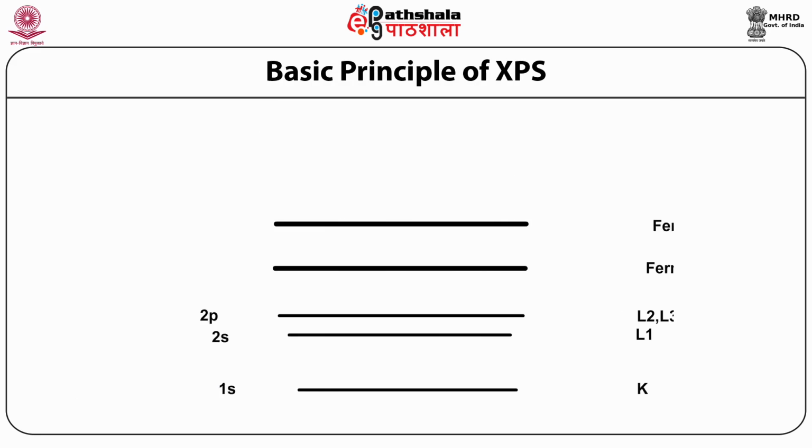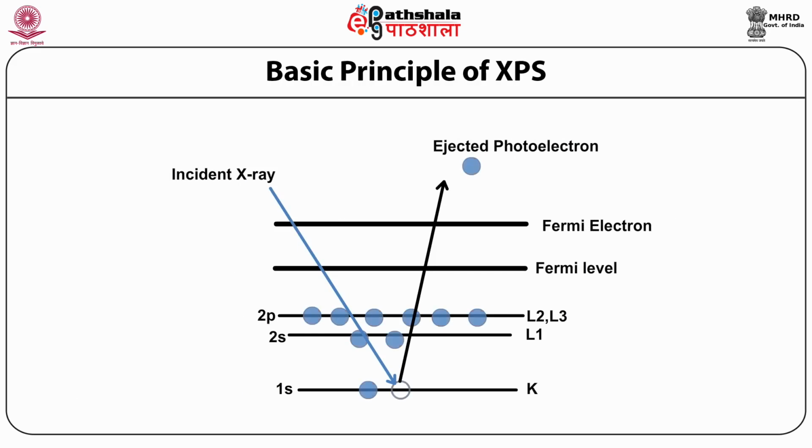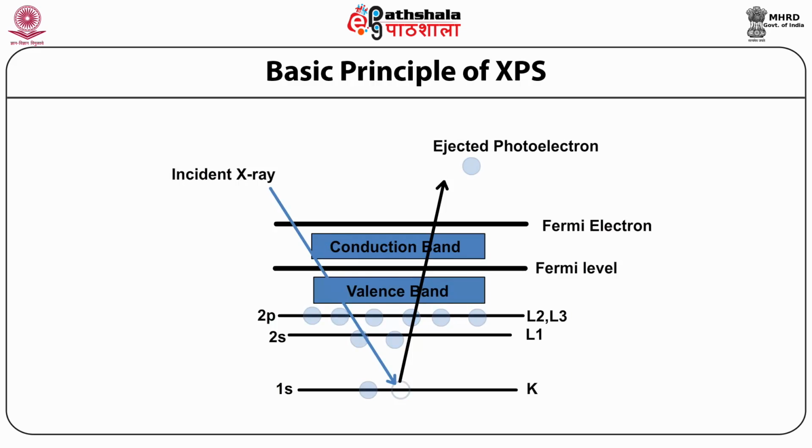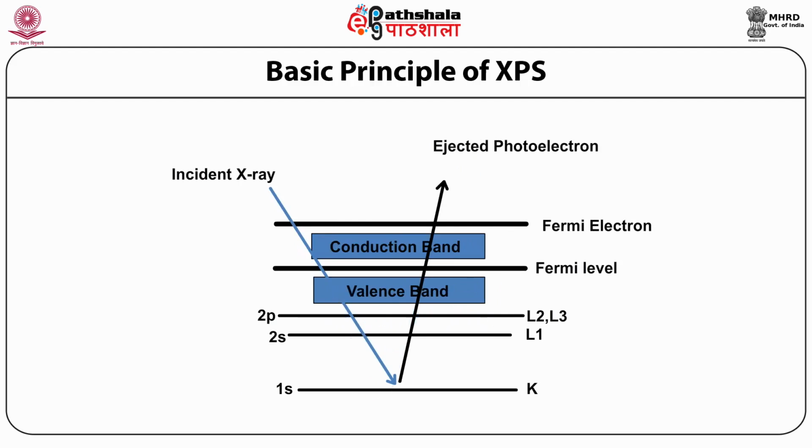In XPS spectroscopy, the photoelectrons can only escape from the uppermost atomic layers of a solid because their energies are relatively low. Thus, electron spectroscopy is a technique for surface chemical analysis due to the short range of the photoelectrons that are excited from the solid.